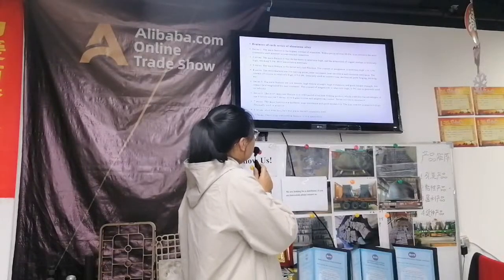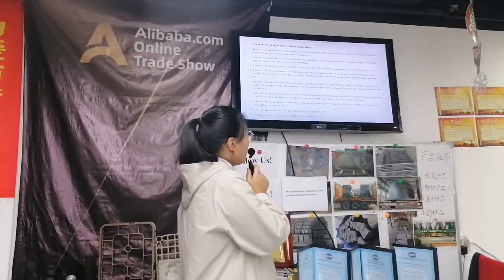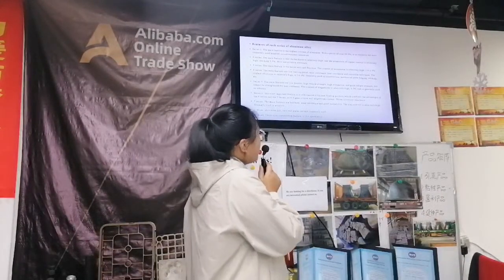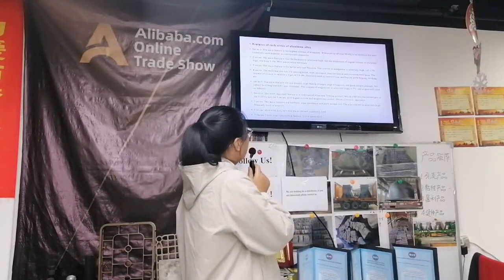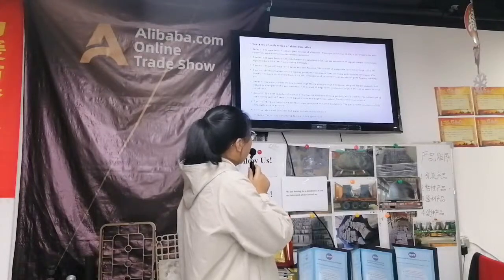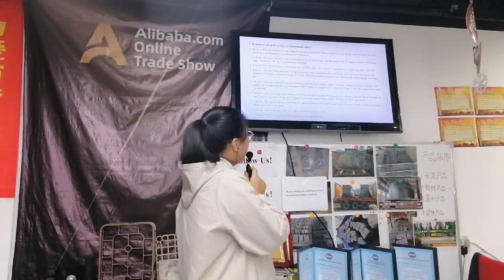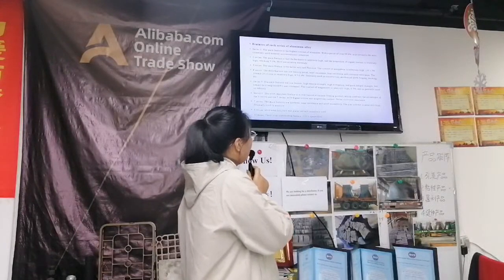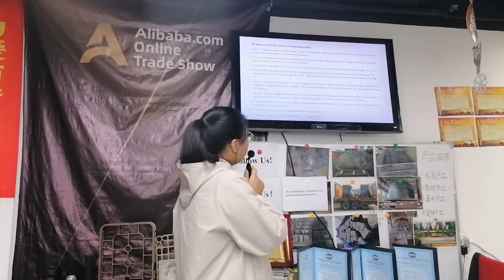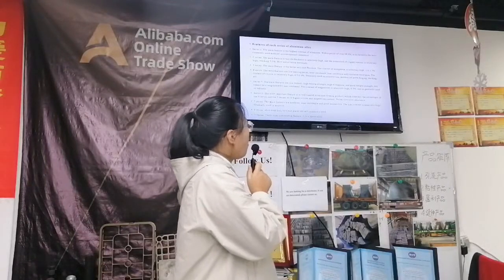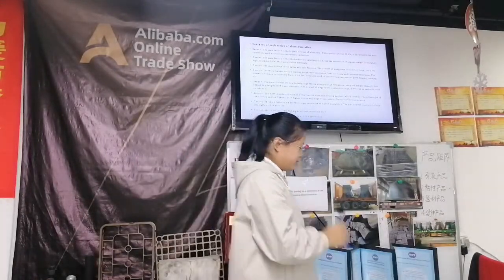7 series: the main features are hardness, wear resistance, and good welding. The zinc content is relatively high, generally used in aviation. 8 series: aluminum foil, bars, and plates are not commonly used. 9 series: there is no outstanding feature. It is a spare alloy.